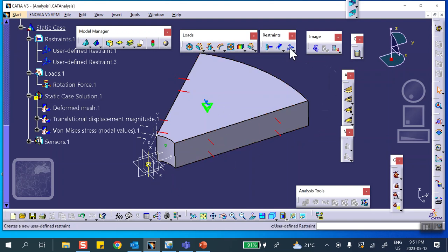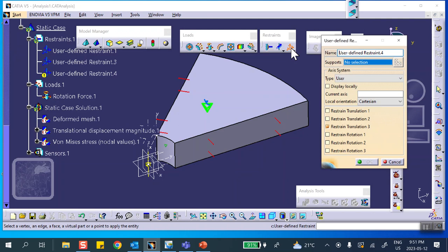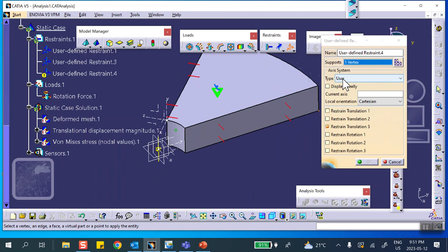But now I'm going to click on the user define on any corner point, this one, somewhere else. You just have to be a little bit careful here, because it is not in the user coordinate, it's in the global one. I want to make sure that it does not move up and down in the direction Z, direction 3, with the global coordinate system.